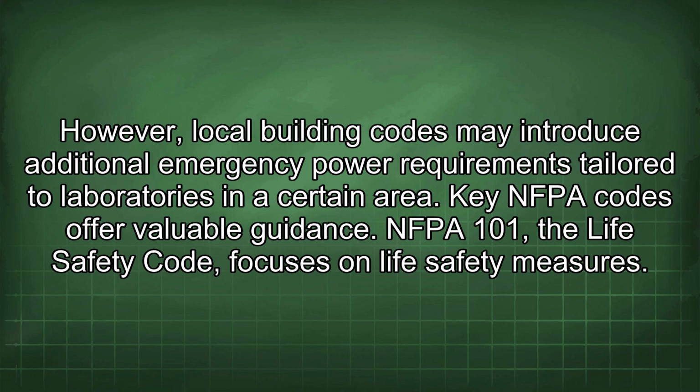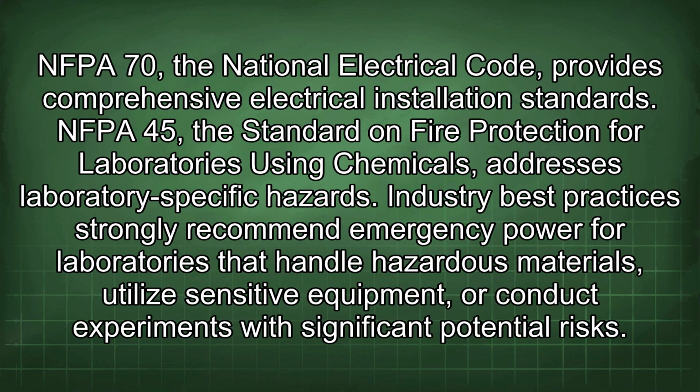Key NFPA codes offer valuable guidance. NFPA 101, the Life Safety Code, focuses on life safety measures. NFPA 70, the National Electrical Code, provides comprehensive electrical installation standards. NFPA 45, the Standard on Fire Protection for Laboratories Using Chemicals, addresses laboratory-specific hazards. Industry best practices strongly recommend emergency power for laboratories that handle hazardous materials, utilize sensitive equipment, or conduct experiments with significant potential risks.